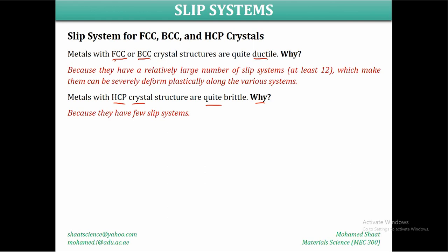But among the metals themselves, some could be considered very ductile. Some of the other metals, in comparison to these very ductile ones, could be considered quite brittle. They could have some ductility, but not that much in comparison. Make sense? So for example, aluminum and copper are very ductile materials. But for some other metals, the ductility in comparison to aluminum or copper is negligible, so they could be considered brittle in comparison.